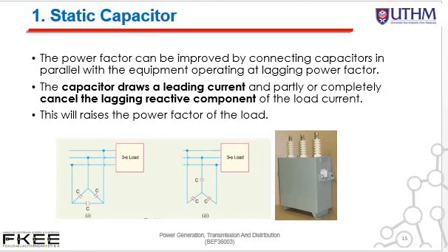As you can see from the figure, the static capacitor improves the power factor of the load by drawing a leading current and cancelling the lagging reactive current component produced by the load itself. Such an application involves a static capacitor either in star or in delta connection.